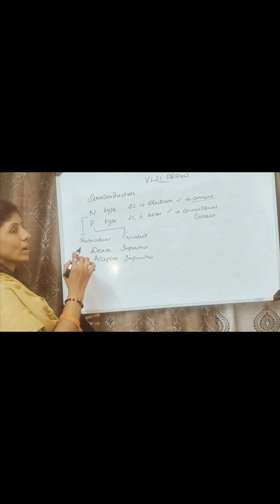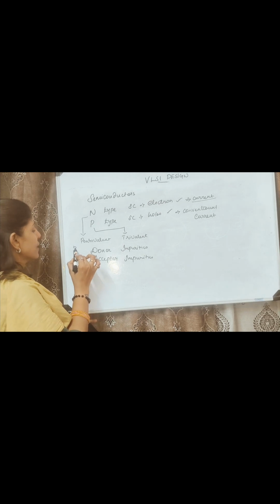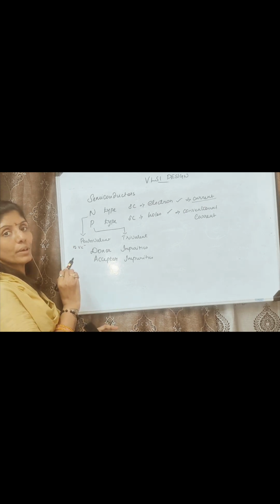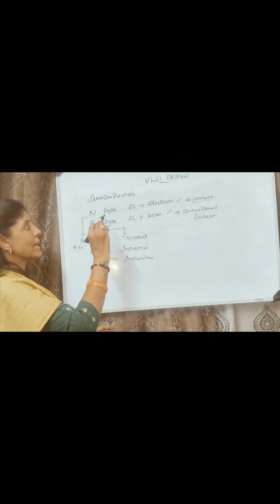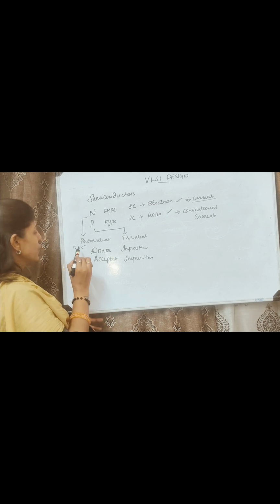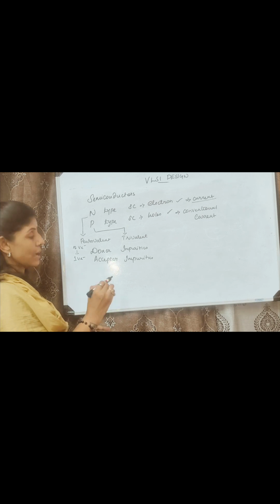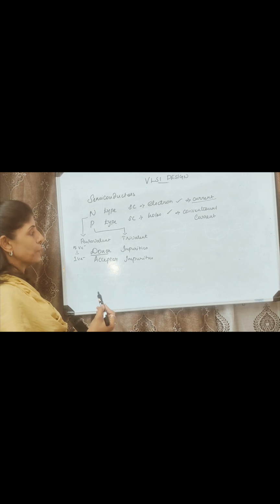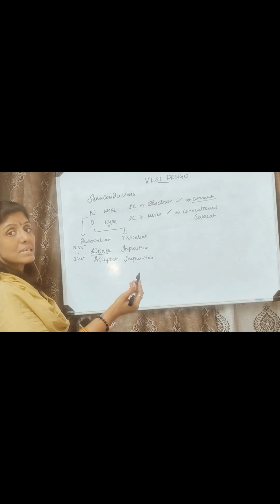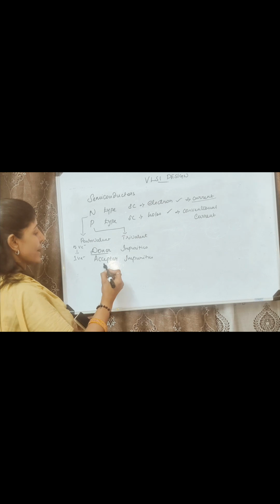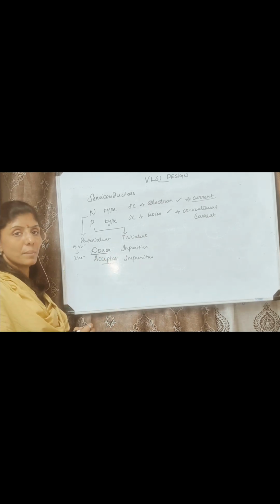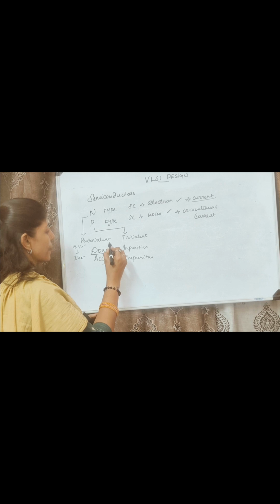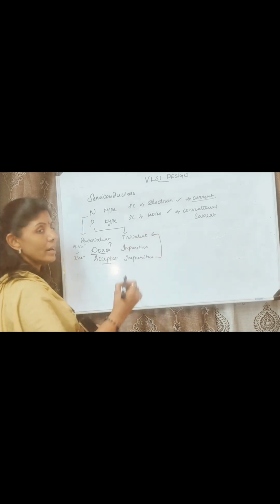In the pentavalent impurity, 5 valence electrons are there. These 5 valence electrons get bonded with the 4 valence electrons of the silicon, so one valence electron from the pentavalent impurity is left. That means it is donating to the host. But the trivalent impurity accepts electrons from the host. That's why it is termed an acceptor, and the other a donor. So donor impurities are pentavalent and acceptor impurities are trivalent.